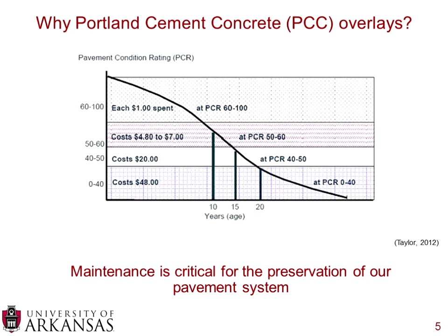This is a discussion that is often talked about in the pavement industry: how do we balance the fact that there is obviously a limited amount of money available for maintaining and building our road network? Is it worth bringing those very poor roads, which are 48 times more expensive, up into a good condition, at the expense of letting other roads further deteriorate? I have a feeling if there was an easy answer to that question, people wouldn't be talking about it. But this is a very nice demonstration of how the further we let roads deteriorate, the more it costs to bring them up into serviceable conditions.